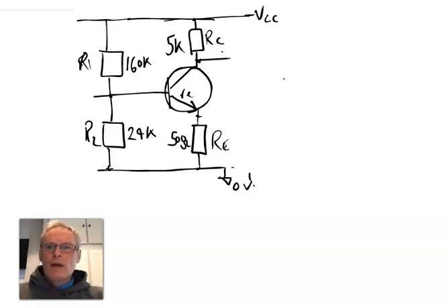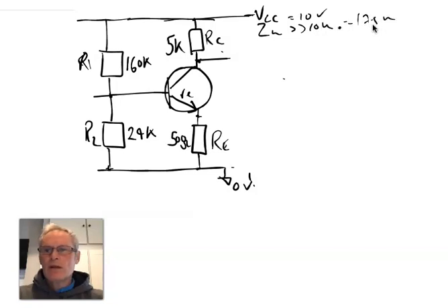So we got to the point where we designed the amplifier and we'd determined that the voltage gain was going to be 10, which was proportional to RC over RE. We also determined that Zin was greater than the 10k, because we said it was around 17.5k, so that was all good. Quiescent current flowing here we calculated as 1 milliamp, so ICQ was satisfied because that was 2 milliamps.